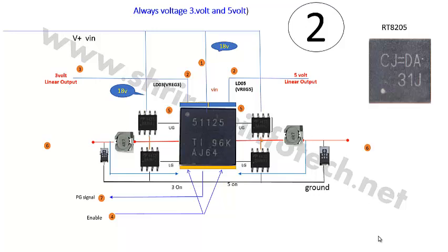In that video we saw how the adapter voltage is passed to the MOSFET and comes across the current sensing resistor, and then this voltage spreads across the entire motherboard. In the motherboard there are various buck converters which generate different voltages.